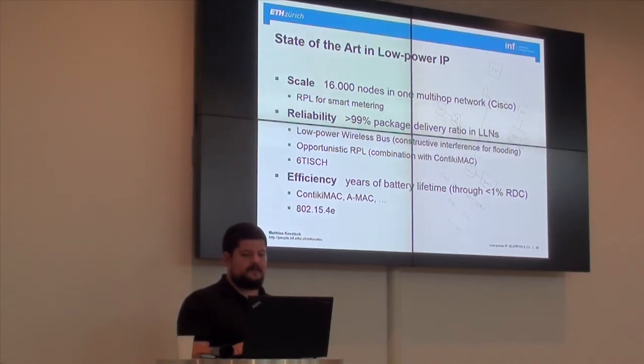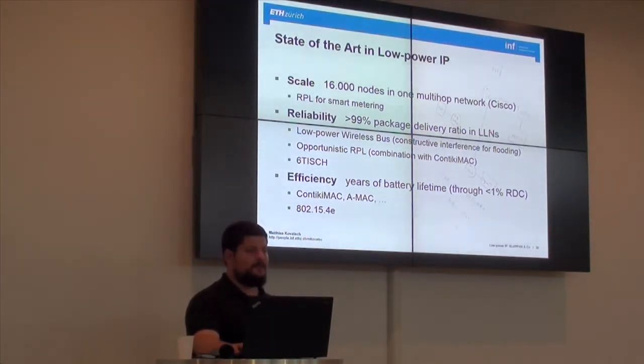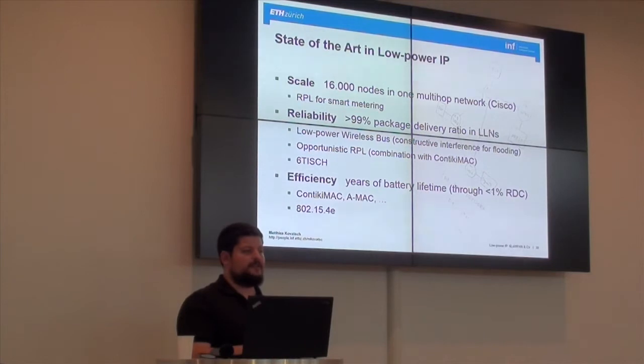And as I said, in terms of efficiency, because you have this really low duty cycle, you get battery lifetimes of years now. There are these academic protocols, but there's also the 15.4e amendment that standardizes that. I'm still waiting for them to just put this in the chip, so that you can rely on it and don't have to do this in software, because the problem is this is really timing sensitive, and usually an implementation just works for this platform where the delays from the microcontroller to the radio or whatsoever are like this.